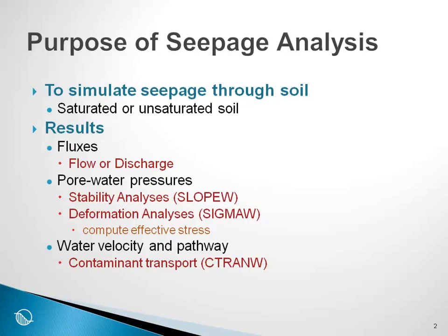In many civil engineering projects, we are interested in pore water pressure distributions. We need to know the pore water pressure distribution for a stability analysis, and we want to use the SEEP/W results in SLOPE/W. We need the pore pressure in order to get at the shear strength if we are going to use effective shear strength parameters.